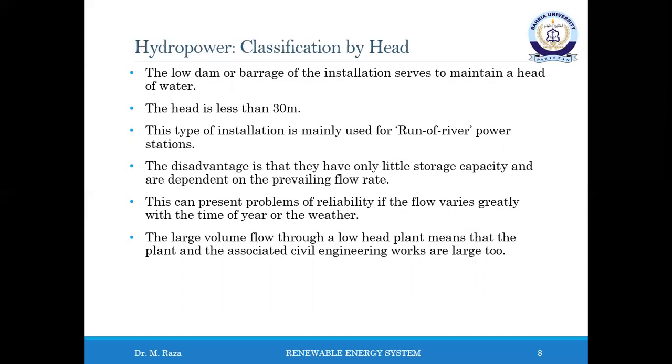Also, classifying hydropower plants according to head may be inconsistent with classification based on power capacity. Power capacity is proportional to the product of available flow and head. Hence, even a high head installation might be characterized as a micro or small hydropower plant.